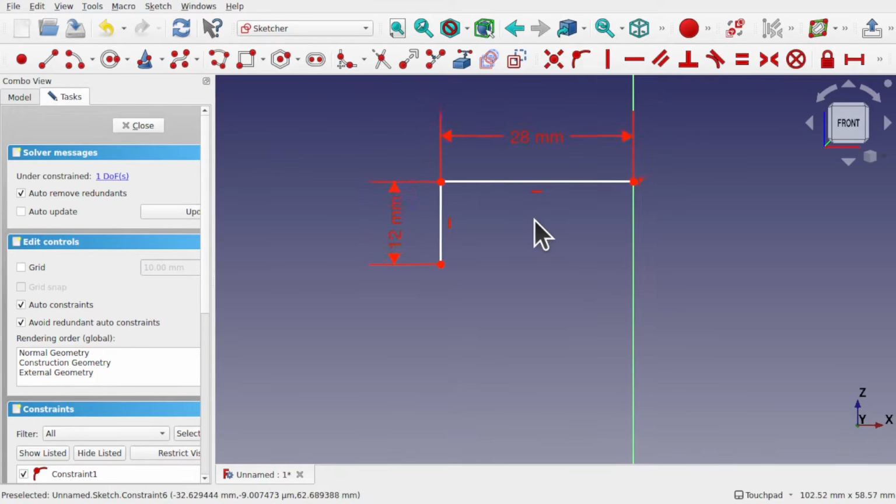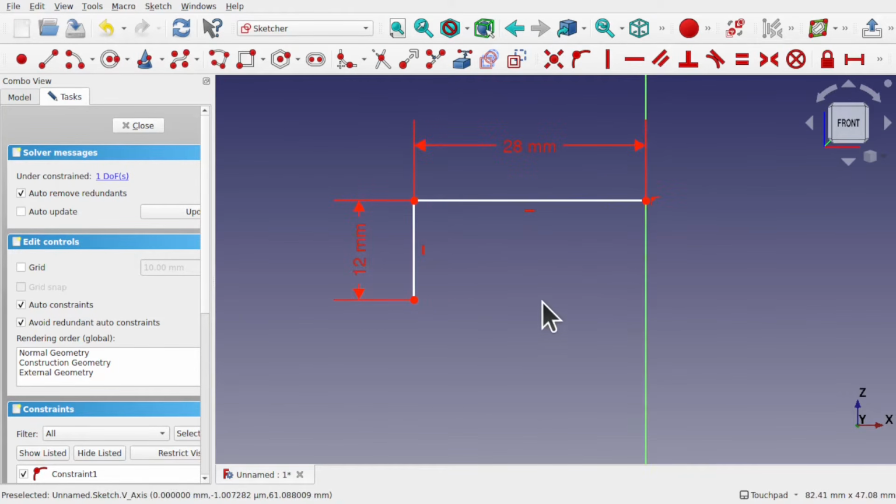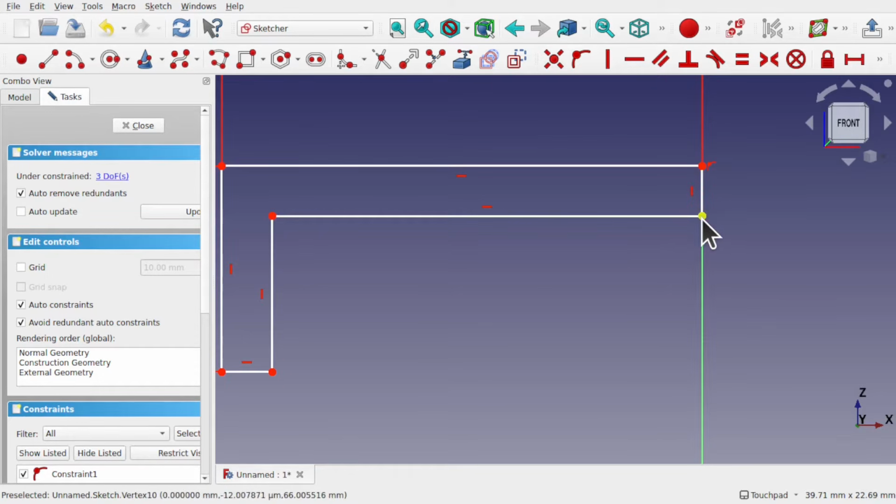This means we can center ourselves and decide where this is going to go. So we can set up our viewpoint. I want to sketch something like this, zoomed into the correct scale. Let's use the polyline again. Because we've got the auto constraints on, if I hover over that, we get a coincident constraint. And we're going to come out and create a piece of wall geometry, and we're going to close the sketch. I'm going to hit escape and clean up my constraints, because this point is on that line where it's on the vertical, so that's fine.